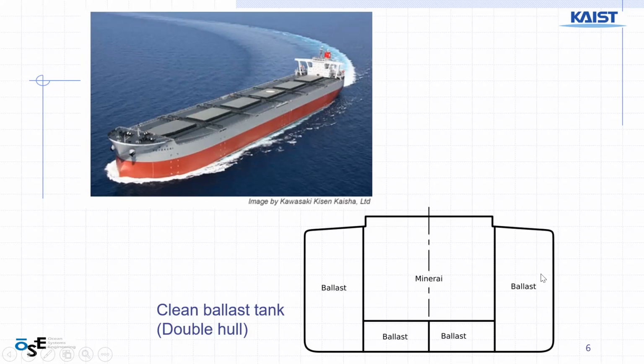And then ballast tanks. A ballast tank is a water tank, which can be used for balancing the position of the ship when the ship is full of cargo and empty of cargo. There are two cases probably for this kind of ship. Say this ship can move to Australia to carry ore stones to Korea or Japan or China.